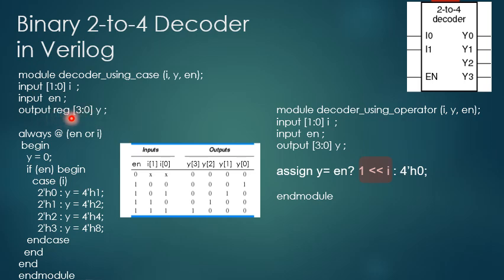And you have the type reg here because you are using a procedural block, and the output Y is also the signal that will be produced by this procedural block, where you notice that Y is also the left-hand side variable under the procedural block. So in this case, the rules of the Verilog data types require us to declare Y as type reg.